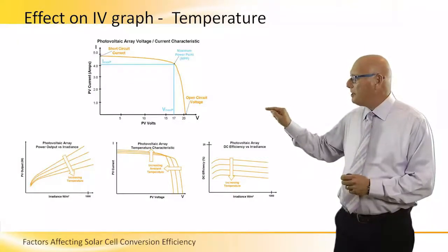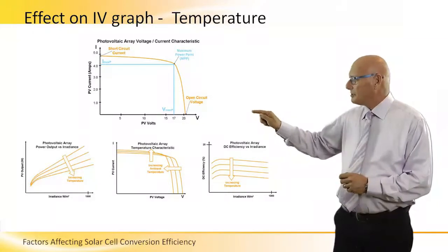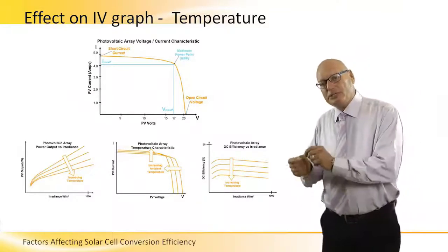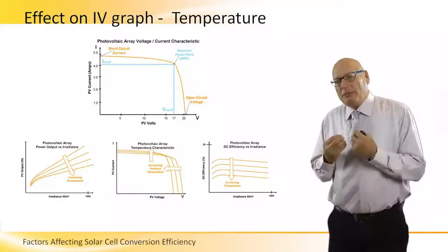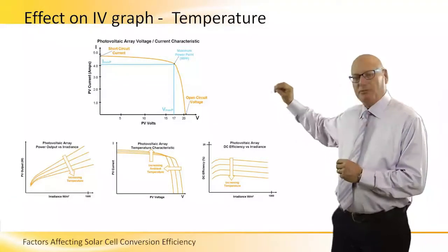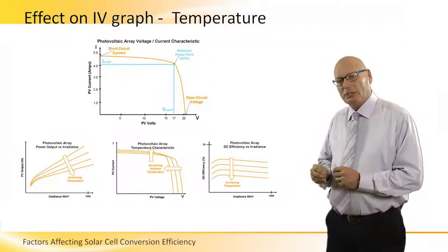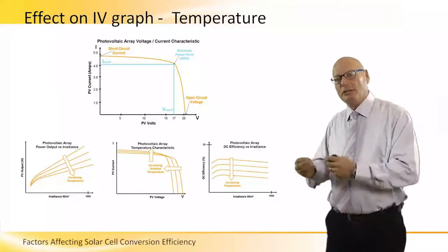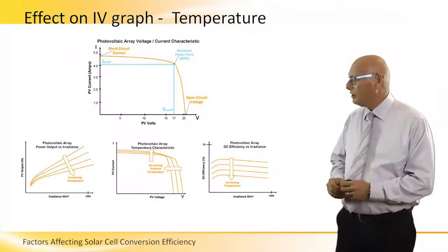And we have an MPP point, maximum power point, MPP, which is the Imax and the Vmax. The multiplication of these two values will give me the maximum power. It's the MPP. And my purpose is to push to the right this MPP point, to make the multiplication bigger. In other words, to increase the current and to increase the voltage, so the multiplication will be bigger, therefore the power will be higher. Let's look at the lower three graphs.